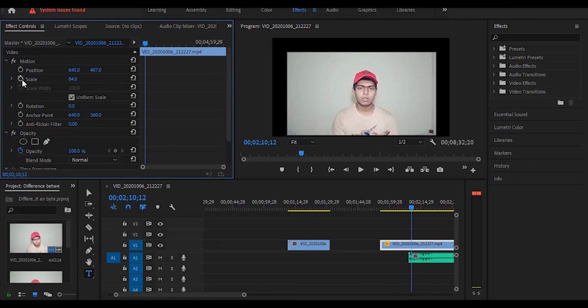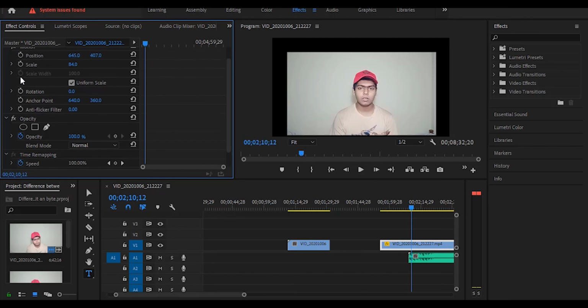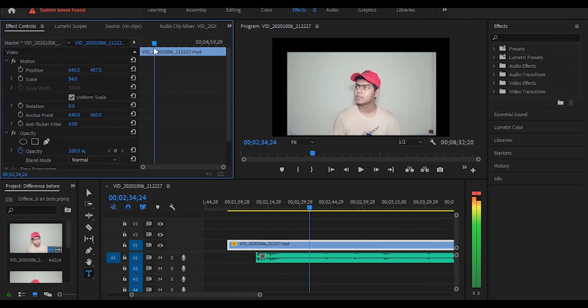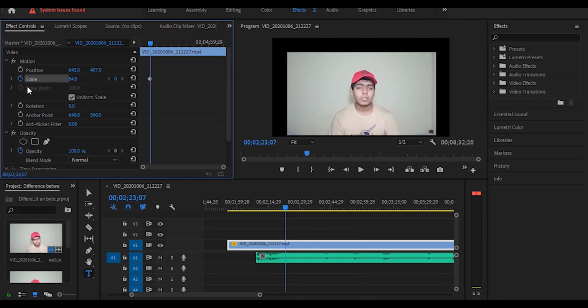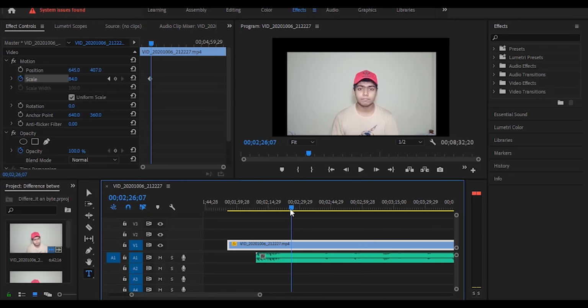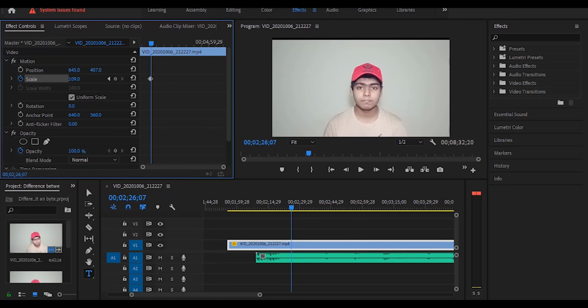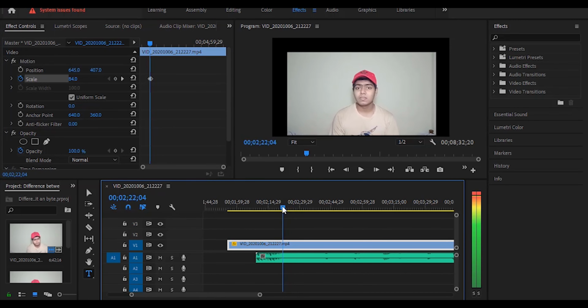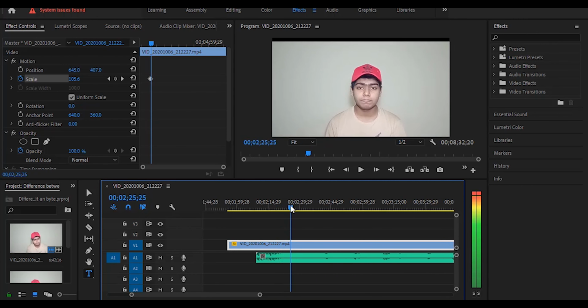and these are the things to make a keyframe. You can click on that and this will create a keyframe which you can control over here. Let me show you. So I have selected a keyframe for the scale, so we can see a keyframe is created over here. Now I click the reset. Okay, you can simply drag it a little bit and increase the scale. So whenever you are playing the video from this place to this place, it will simply zoom.